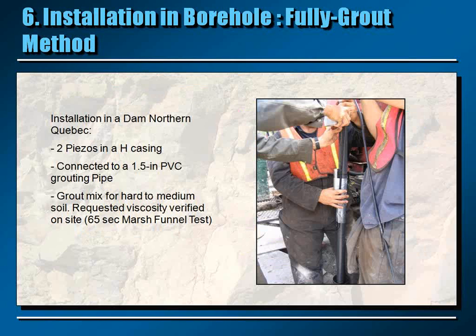Okay, this picture was taken from a job that we did during installation of piezometers following the Fully-Grout method. We were at a dam construction site in northern Quebec, where 2 piezometers were installed in each borehole, and we were using H casing.